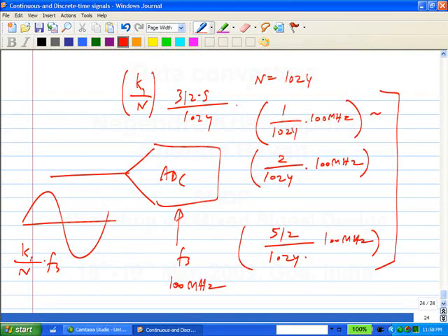You have a 100 megahertz A to D, then in 1 second you have 100 million samples. Whereas to simulate for 100 million samples, you put your computer through for a month, it will still not be able to do it. So it's even more important in simulation. Maybe in simulation you can simulate your complicated circuit for maybe 1000, 2000 points. So the input frequency has to be chosen correctly.